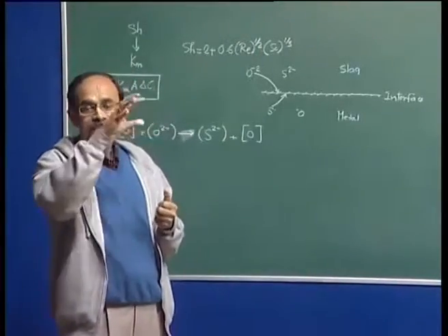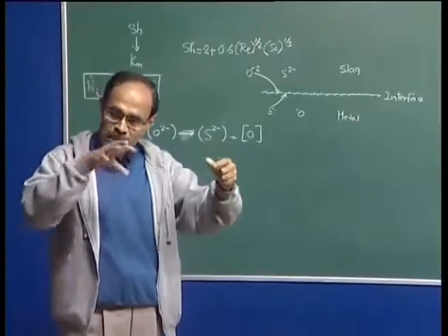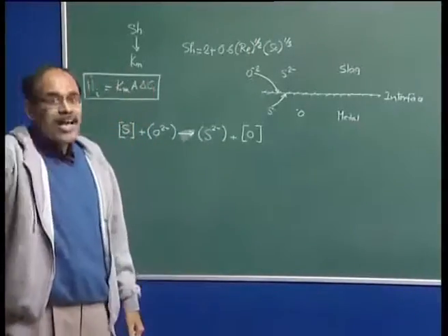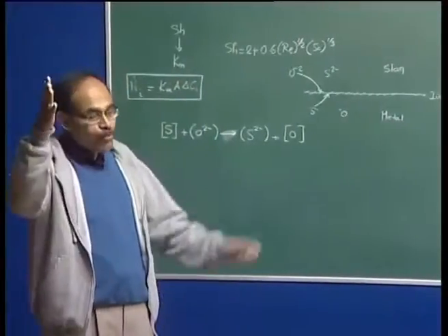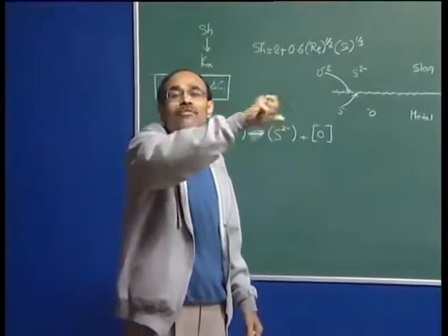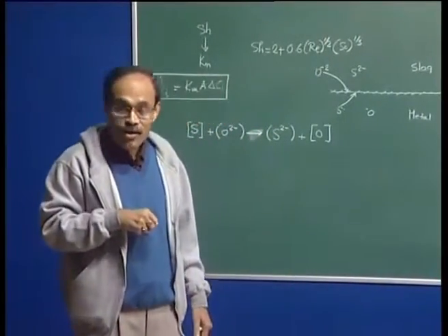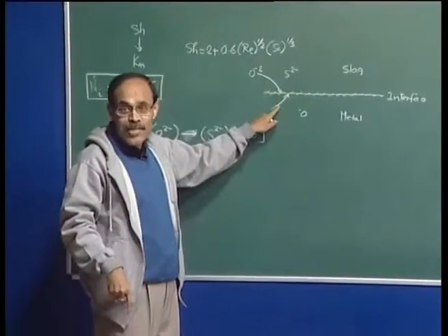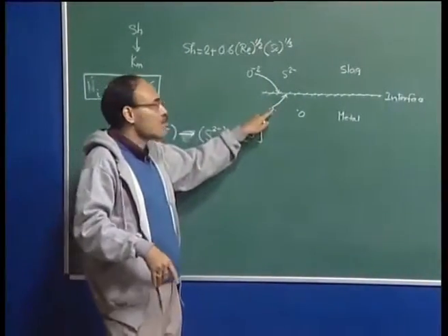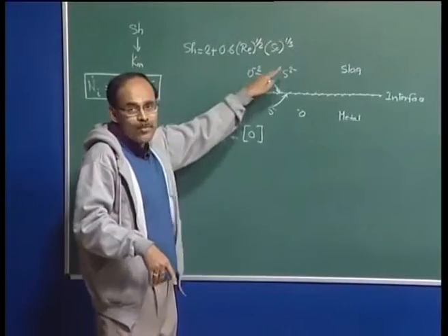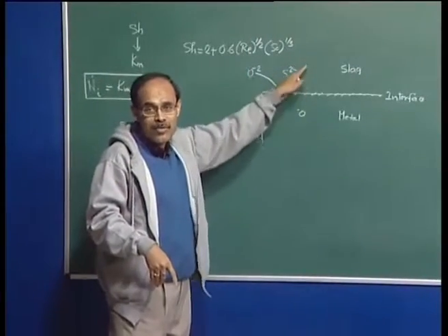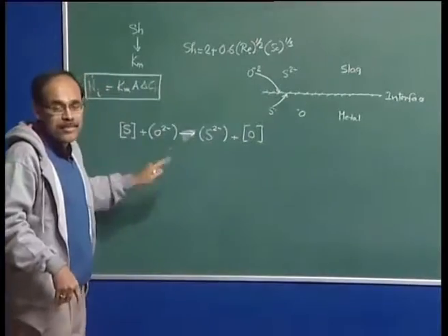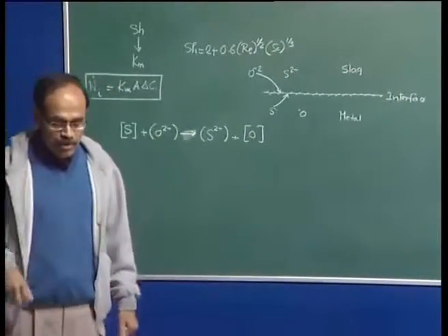So, these are the time taken for the 3 individual steps, and the total time that you take to reach the classroom from your hostel is a summation of all these activities. Similarly, the overall rate of desulfurization here is the summation of the rates of the 4 mass transport steps, 2 in the metal phase, 2 in the slag phase, plus the chemical reaction.